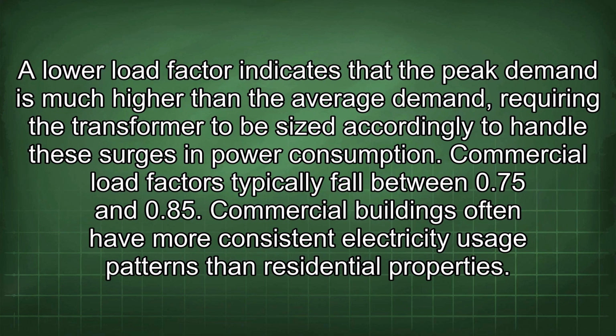A lower load factor indicates that the peak demand is much higher than the average demand, requiring the transformer to be sized accordingly to handle these surges in power consumption. Commercial load factors typically fall between 0.75 and 0.85. Commercial buildings often have more consistent electricity usage patterns than residential properties.